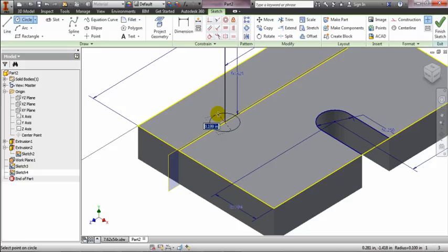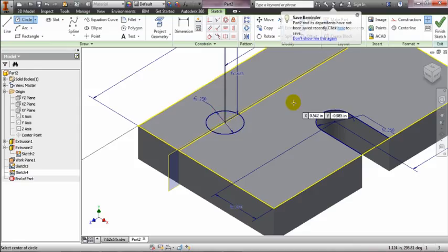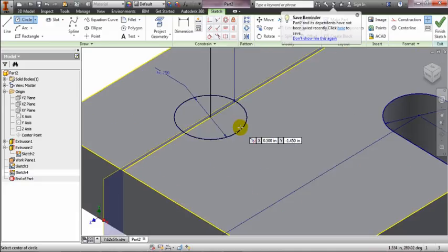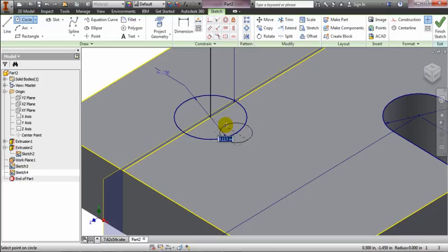also 0.25. But I don't want to type 0.25. I'm going to put D0. So it's just going to be D0 again. Now I'm going to lock on to this point right here, the edge of my circle, and I'm going to make this also D0.